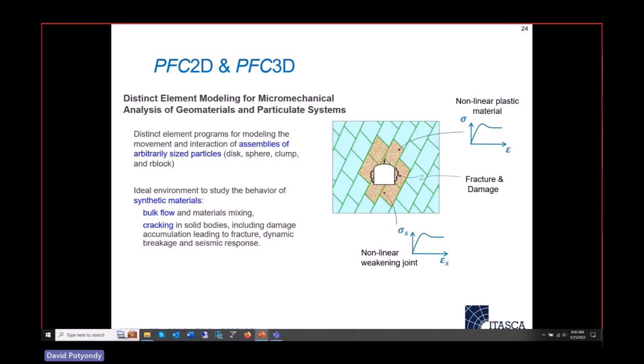These are the fundamental particles that can then interact and move around and be glued together that we support in PFC. Again, the main people that are using PFC are using it to do basically rock mechanics type research, where what we really do is we're creating a synthetic material. Any PFC model where you bond these things together could in principle be constructed in the physical world, which is really interesting. If you have a constitutive model in a continuum code, that material is a complete mathematical continuum mechanics idealization with plasticity theory. You could not directly physically construct such a material in the real world.